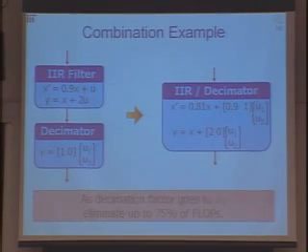And actually, if you do a lot more: the first decimator basically eliminates one value, so it's only looking at one result. If the decimator eliminates a lot of values and only looks at some, because a lot of times in DSP algorithms that's what they do, you downsample. You only look at every 100th value. Then you can almost eliminate 75% of all the computation. So neat. You can do optimization and get rid of a huge amount of computation.